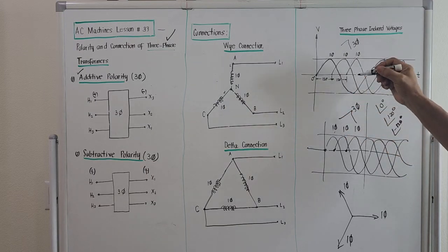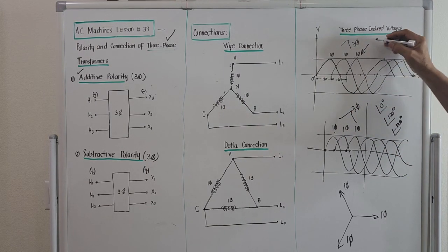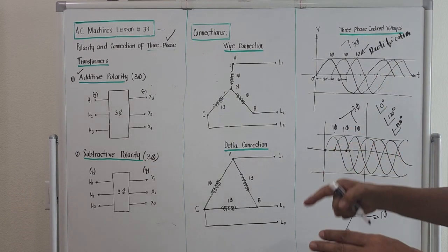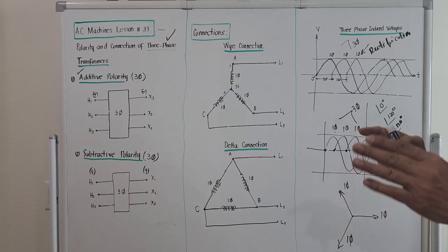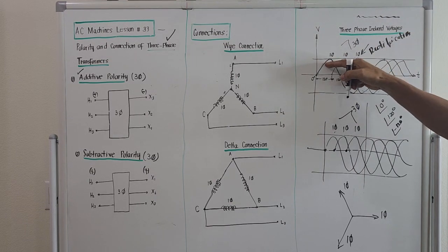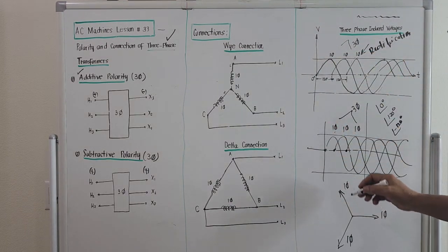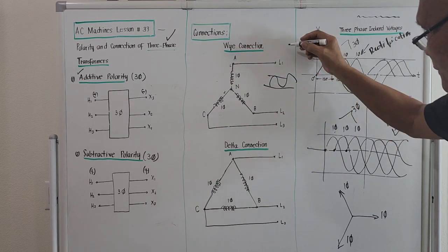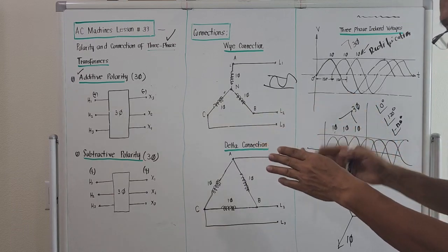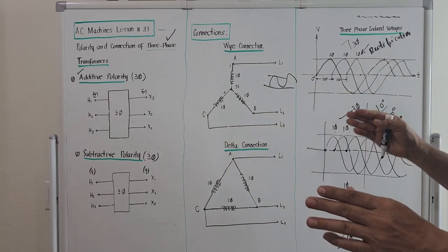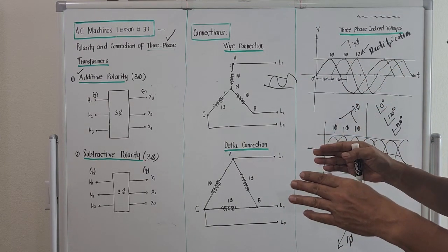So actually, if we try to use this in the so-called rectification, in the rectification of alternating current voltages to direct current, for a three-phase, the output will be smoother, you know. But for a single phase, it's just alone, it's just one like that. So if you try to rectify it, it's much rougher than for a three-phase. So, actually, three-phase is good for rectifying voltages, right?